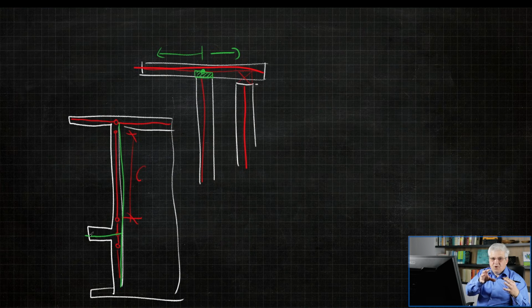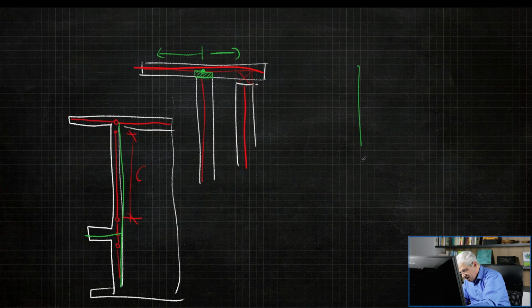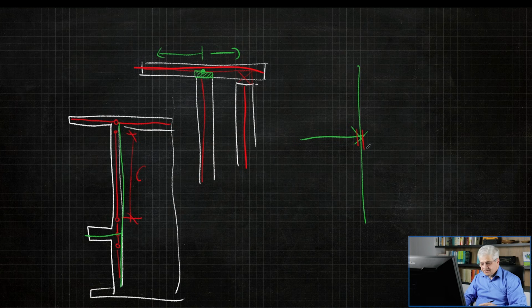If you create 1D elements and you create one line and second line, then it's automatically connected in SCIA Engineer with this double red line. But this is not the case in the cross-section design. You have to split the lines. You can draw one line and another line, or you can draw one polyline, but you have to create this one point where it should be connected.